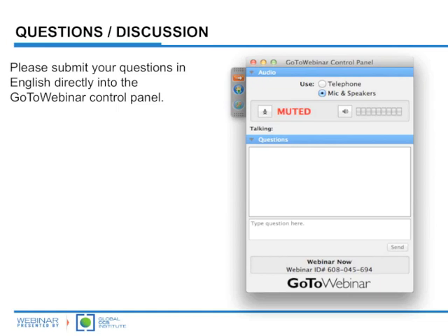Now, for R&D people and engineers across the board who just want an idea of how the system would work, but do not have access to maps or don't have a vendor selected yet for the compression side of things, we've also incorporated a mechanism that allows you to use a reference map, something that applies more or less to 70% of the rotating equipment that is out there.